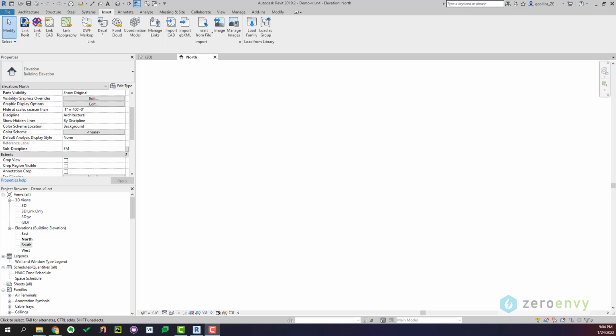So the first step is to link an architectural Revit model as a background in our blank Revit file. The whole idea here is that we want to have this background and we can trace it. It is really hard to directly export an architectural Revit model to a gbXML file. Usually you will just run into a ton of errors. So we just wanted to have this background and we can trace it to create a cleaner geometry that we can export to a gbXML file successfully.